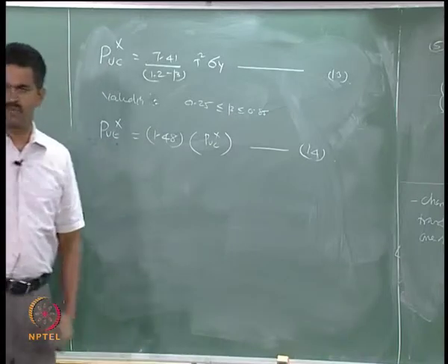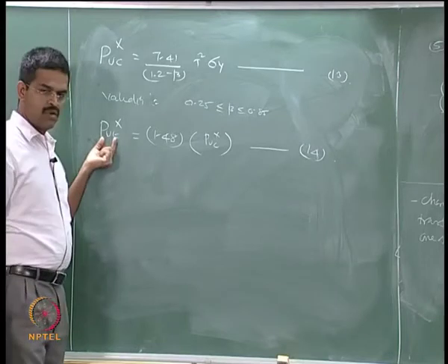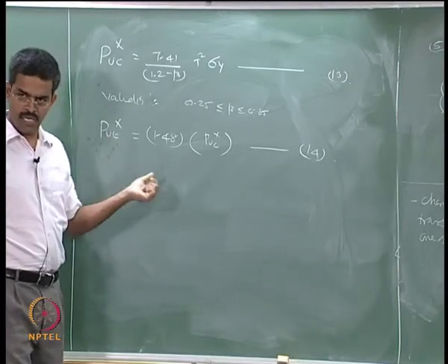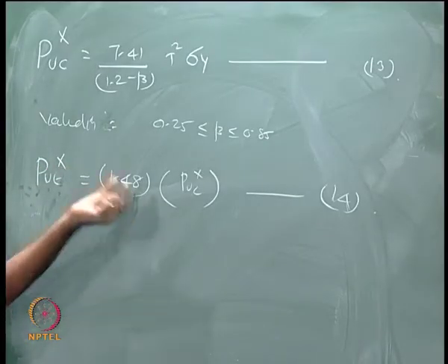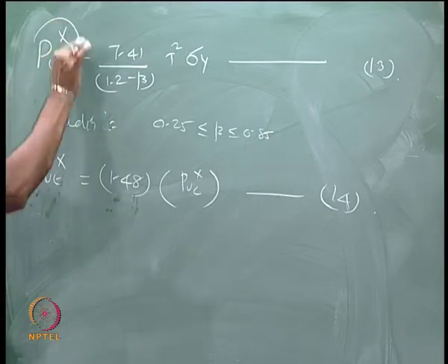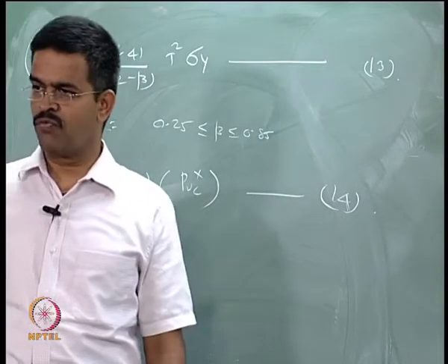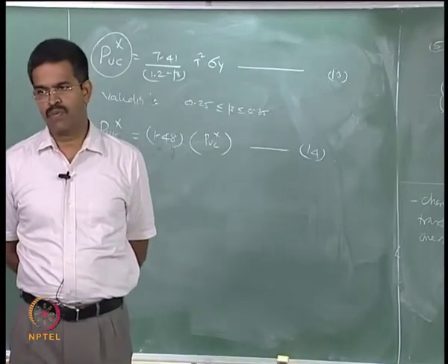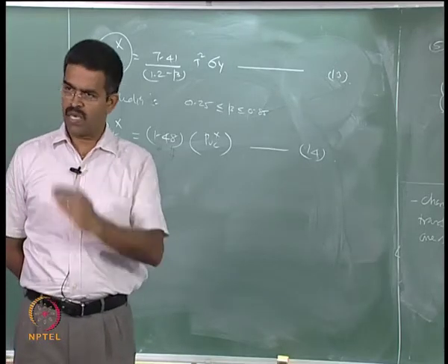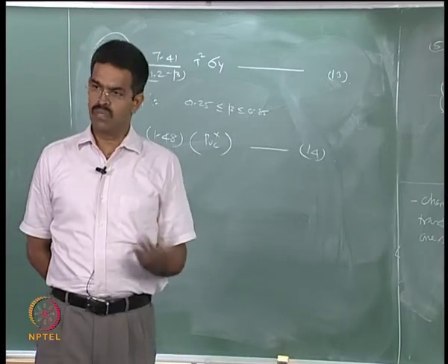So, you can very well see here in most of the experimental results it has been observed that the ultimate strength of any joint, be it Y, be it T, be it X, be it K, the strength in tension is slightly higher compared to that of compression. That is why compressive force governs the design of tubular joints, because the failure is a combination of plastic hinge formation with that of the stability in case of T joints as well. And you will always see in case of Y, in case of K, they are equivalently converted to T.